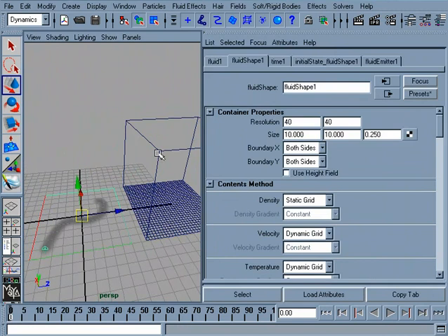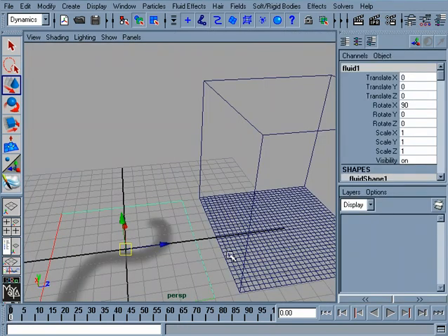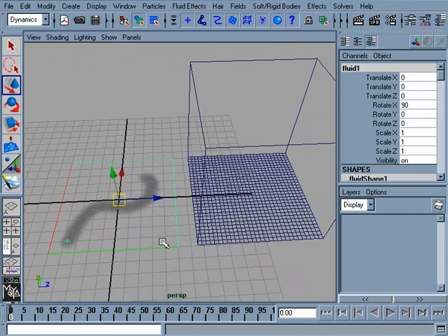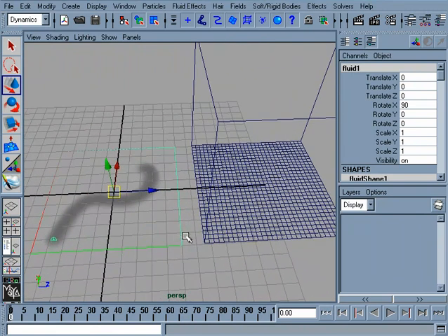Okay, now here's the basis of what we'll be doing with this expression. Each one of these containers is actually made up of voxels. So what we'll do with this expression is basically say, okay, in voxel number 1, let's check if the heat is existent. If there is no heat, move on. Check voxel 2. If there's no heat, move on. Check voxel 3. If there is heat in that voxel, go ahead and ignite the corresponding voxel in this container.